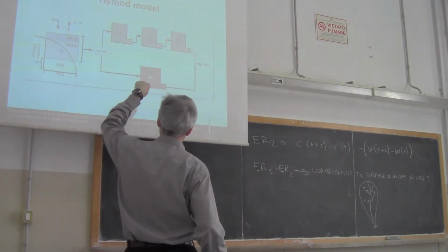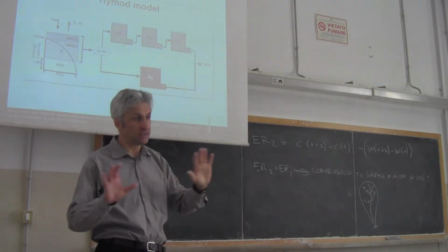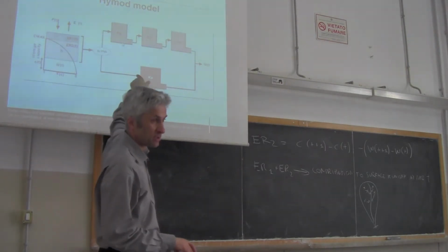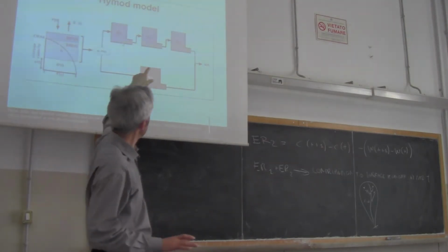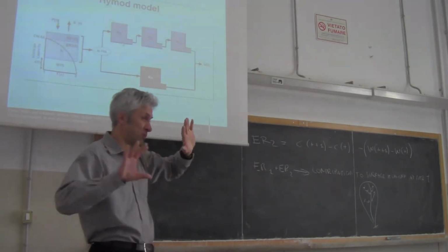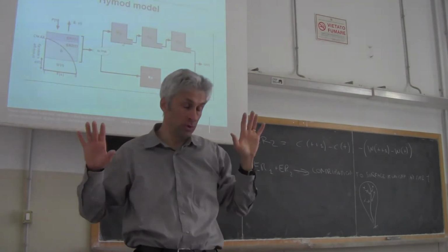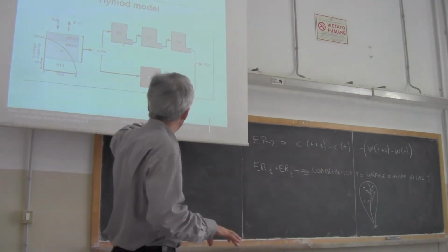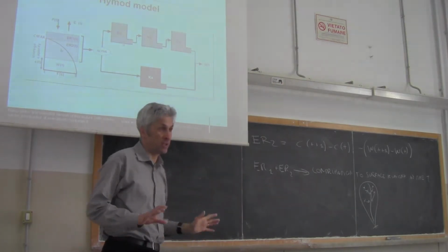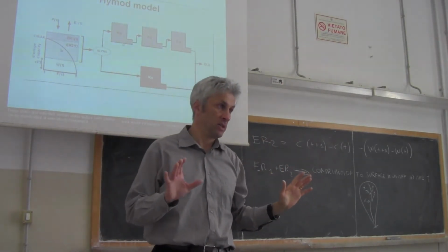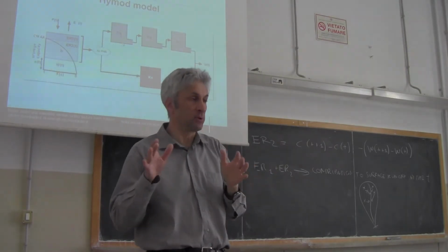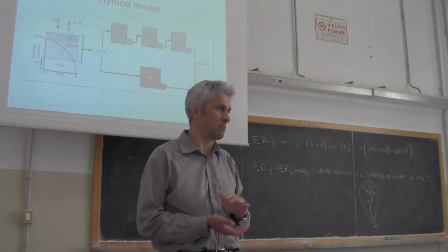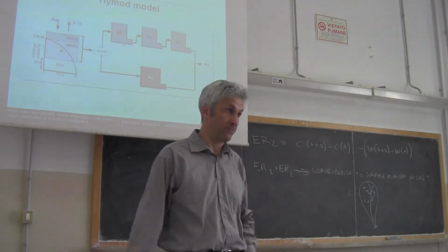And for applying the linear reservoir, there is a very simple analytical relationship to be applied at each time step that gives you the outcome depending on the input. And also for the sequence of 3 linear reservoirs, it's a very simple relationship. Those of you who already have a background in hydrology know that this is nothing else than what is called the Nash model. Very simple analytical relationship to apply it. So it is just a sequence of very simple instructions and a code that is less than 1 page long. We will see it.